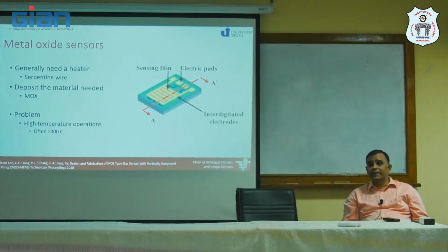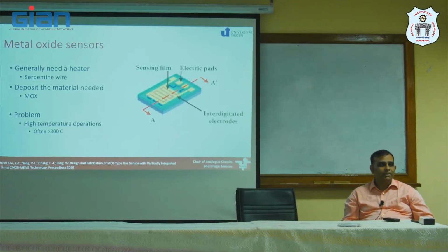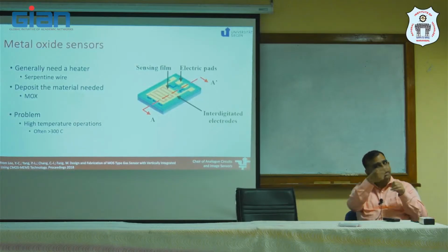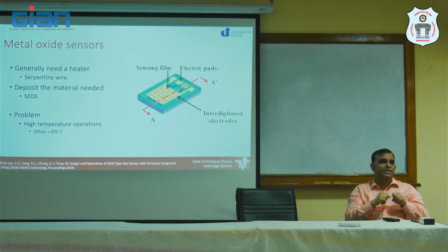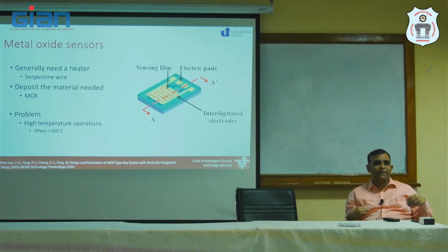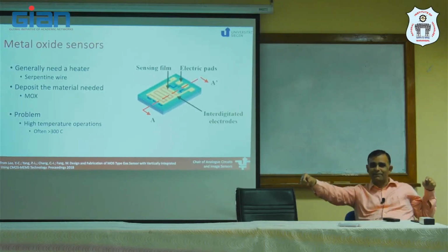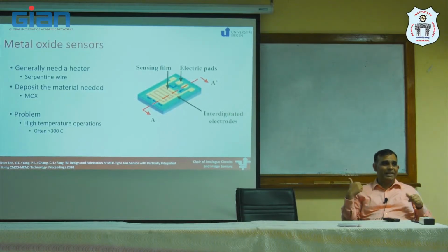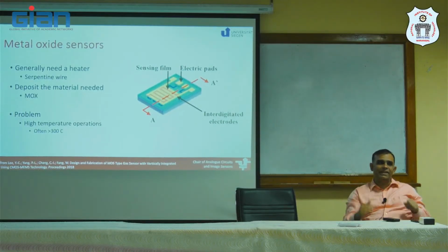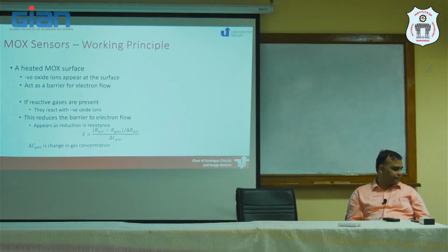If you look at the number of heater designs, now we are in the mechanical engineering domain. Right? Heaters can be designed in many ways. Which serpentine wire to go with? Do we go single loop? Do we do double loop? Do we do square loops? Which side do we fit? This is all mechanical engineering domain. Now we generally draw wires. Yesterday when some of you were doing layouts, you drew straight wires. We like straight wires because, well, we are electrical engineers. But when you want to make a heater kind of structure, then you start playing with what the thickness should be, what the length should be, and then a large number of different approaches can come in.